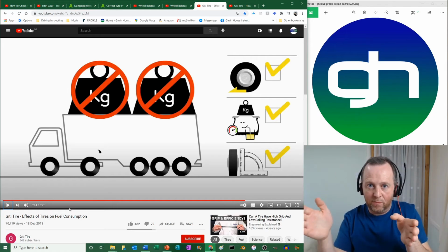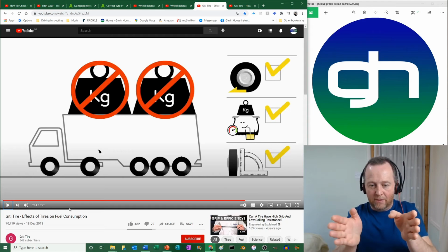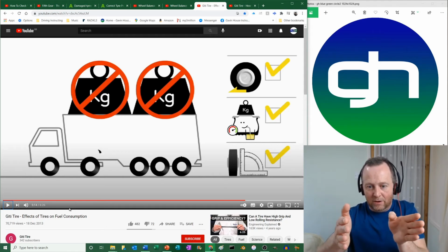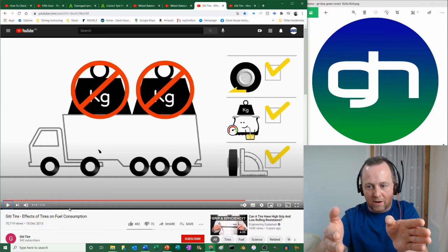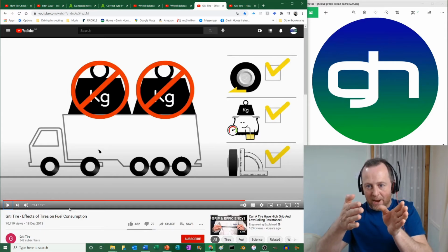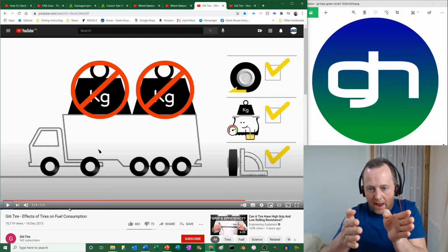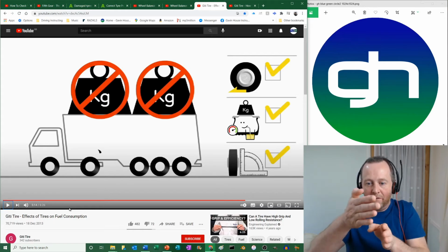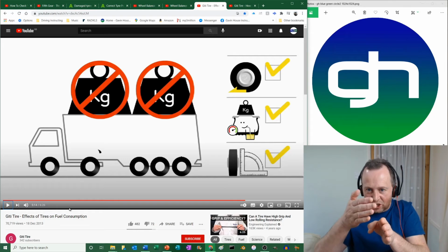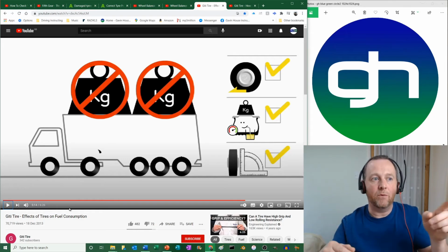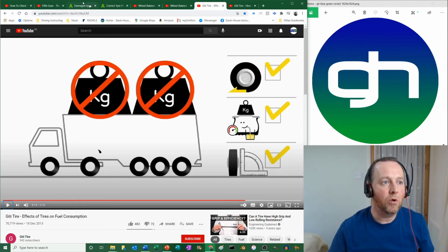But if you're steering to the left to put it back, you're actually driving down the road steering left just to try and stay in the straight line. So your wheels are pointing that way to counteract the fact that it's naturally going that way, but you're going forwards. So therefore your tyre isn't rotating, it's actually scrubbing on the floor. And that's how we saw the tyres earlier on.